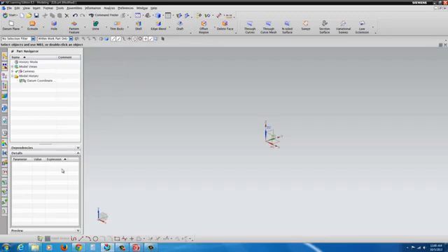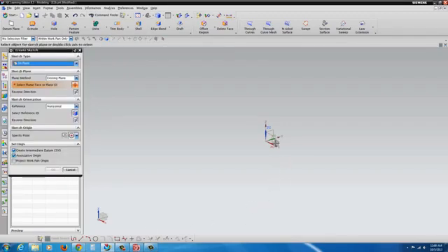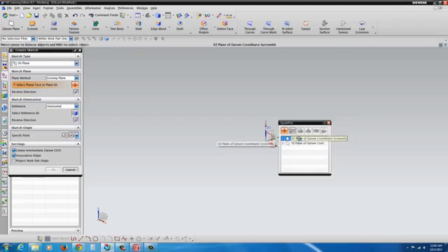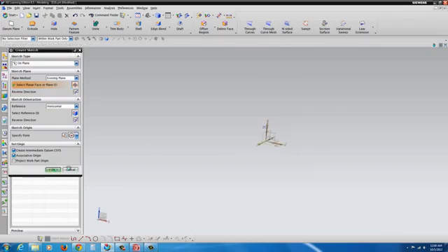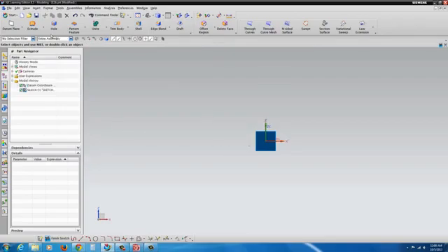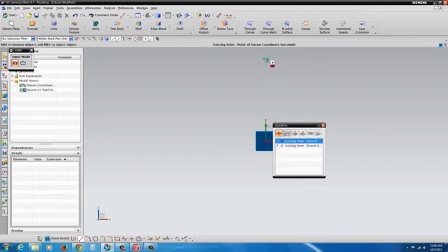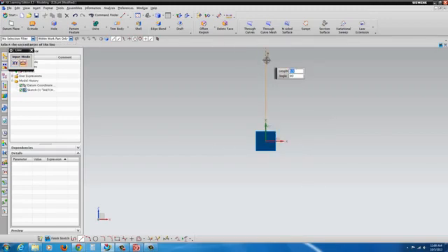And we'll begin into the sketch tool and sketching the XZ plane. Hit OK. Now we're going to take and draw a vertical line at the origin. Don't worry about the length. I'm going to draw a horizontal line from the origin. Again, don't worry about the length on those.